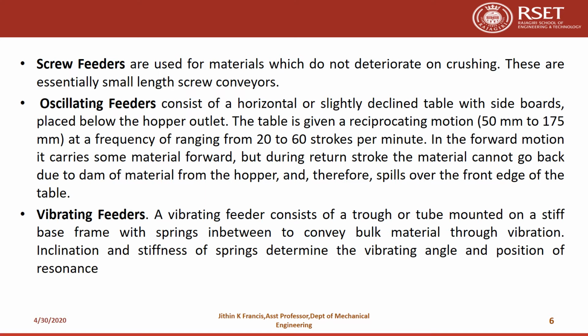Next one is vibrating feeders. A vibrating feeder consists of a trough or tube mounted on a stiff base frame with springs in between to convey bulk material through vibration. Inclination and stiffness of the spring determine the vibrating angle and position of resonance.